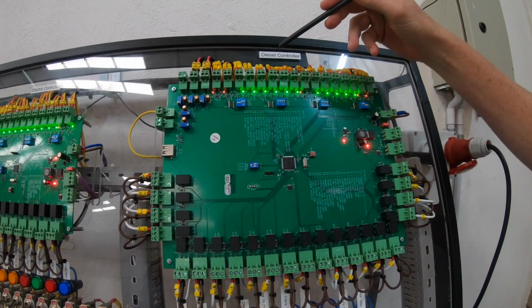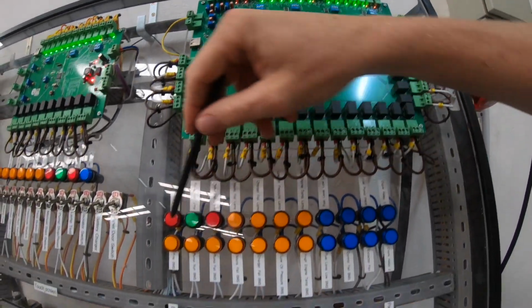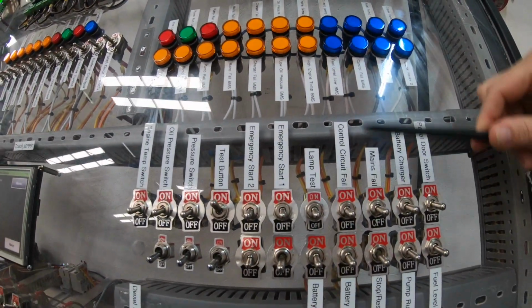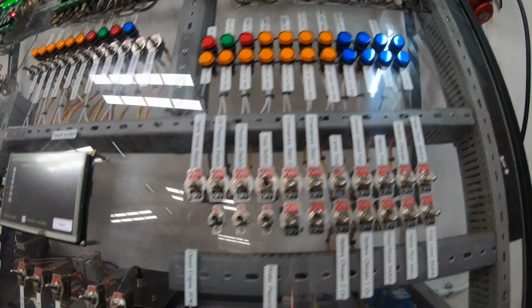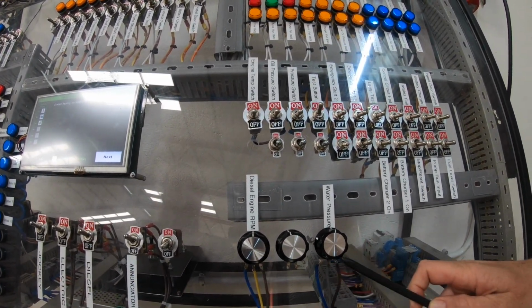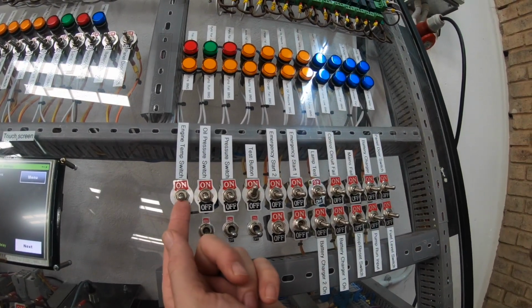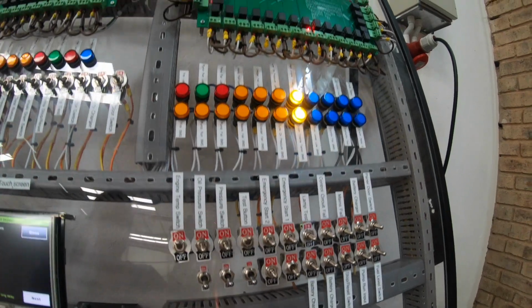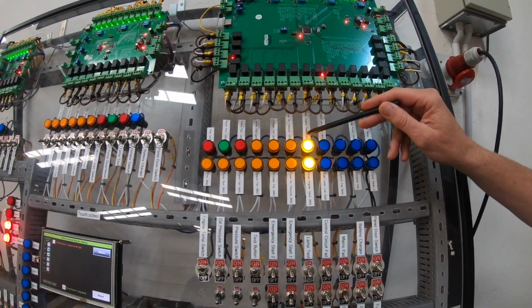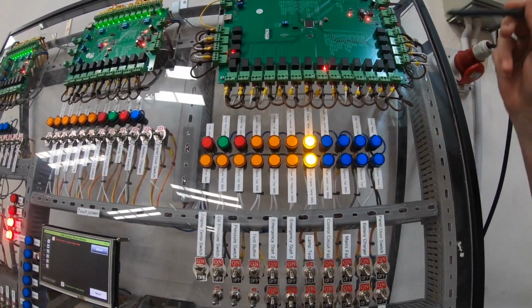Now we're on the diesel controller. We're going to activate the inputs, the outputs, which indicate on these LEDs, and we'll switch them on and off via the toggle switches, as well as the dials to simulate the RPM and the water pressure change on the system. We're now going to activate the engine temperature switch, which activates the LED, the output, high engine temp for the auxiliary and for the output on the controller.